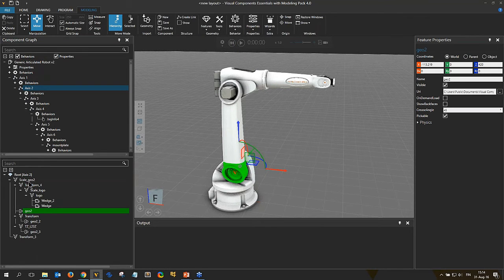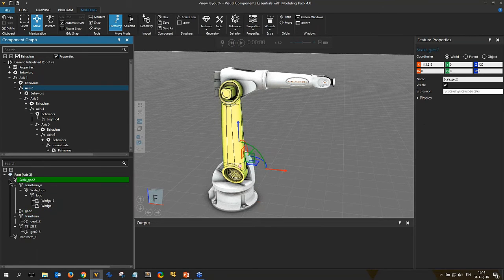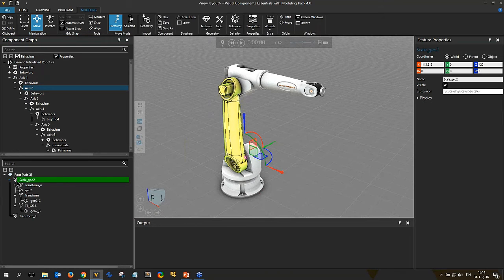All of these features seem to be grouped under one grouping feature called transform. We're going to talk more about these later, so don't worry if you are a bit lost at this point. So this groups all those together, and if I'm in hierarchy mode and I want to move this feature, I will move that feature plus everything underneath. So I will also move the hierarchical children.